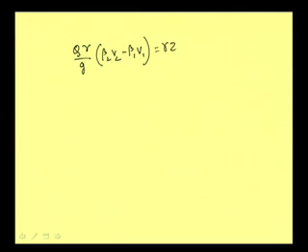This is equal to gamma Z1 bar A1 minus gamma Z2 bar A2 plus W sin theta minus Fe. This is our equation. So, this is basically a momentum equation, and of course we can write it in terms of rho also, but in this form also we can write. There is no difference between these things.